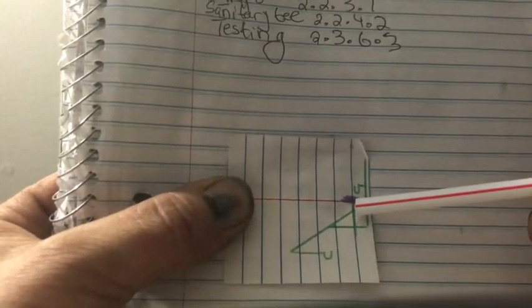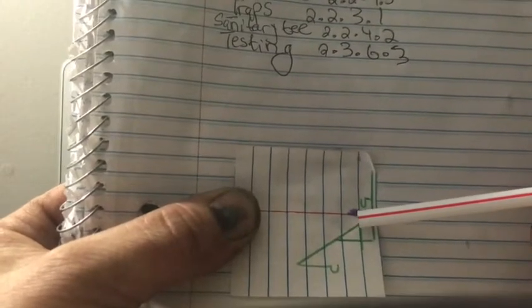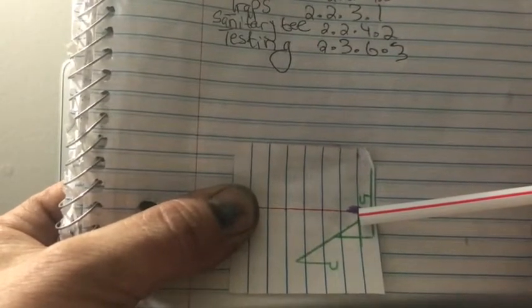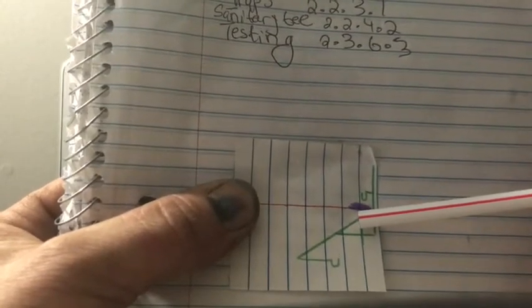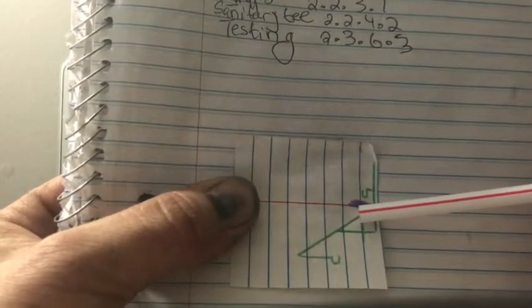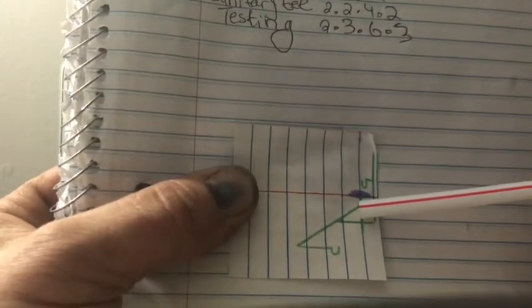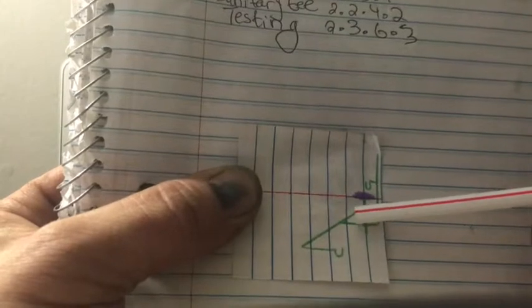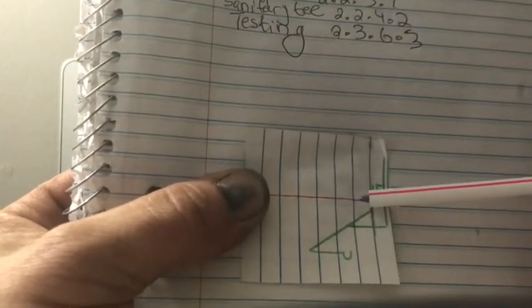So he told me that we can't connect 3, we have to have the stub, which is obviously the hub fitting that comes down through the floor. We put a piece of pipe in it. The piece of pipe, by the time it was glued, had to have a space of at least 3/4 inches in between our 3x2 sanitary tee that's serving as a wet vent here to wet vent this water closet.